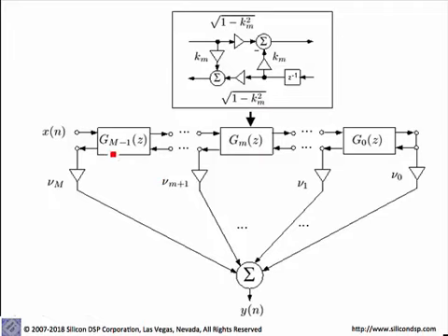Now we take the input, and as it goes through this lattice structure, there's also feedback. As you can see, we feed it back here, and then the outputs of the feedback are weighted by the weights shown over here, and they are all accumulated and added up to form the output y sub n. So x sub n and y sub n in an ideal infinite precision will match, for example, the direct form or cascade form implementation of that IIR filter. But that's an ideal infinite precision.